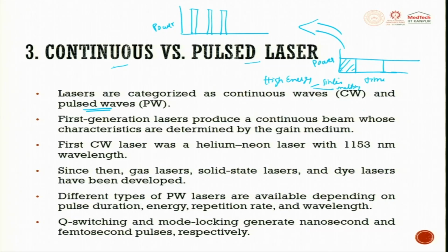the circuit also need not be as robust as that of continuous. In continuous, after a certain peak power, it becomes very inefficient. Today, for the continuous laser, we are talking about efficiency somewhere close to 15 to 20%. So, if you apply 1 kilowatt of energy, you can get only 200 watts which is useful, which comes out of the laser, which will then get into the system. So, finally the efficiency will boil down to 3 to 4% only. That is why people are now using pulsating lasers.